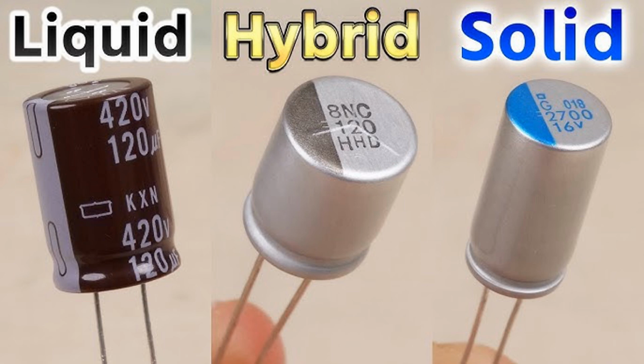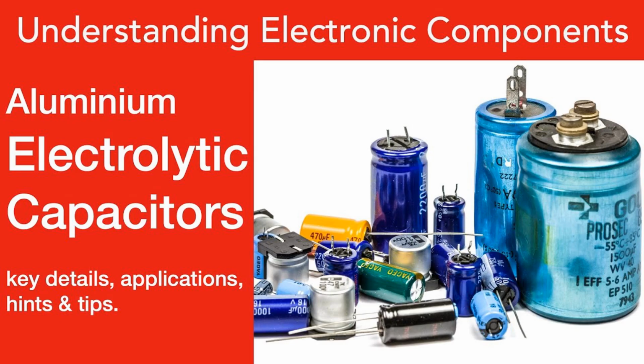Decoupling capacitors are used in power supply circuits to filter out high-frequency noise and ensure a stable voltage supply for sensitive components. Example: in digital circuits, decoupling capacitors help reduce noise caused by switching transients and maintain stable voltage levels for microcontrollers and logic gates. Microcontroller power management. Decoupling capacitors stabilize the voltage supply to microcontrollers and other digital components, preventing noise and ensuring reliable operation. Example: in a microcontroller-based system, decoupling capacitors placed near the microcontroller's power pins prevent fluctuations that could affect performance.